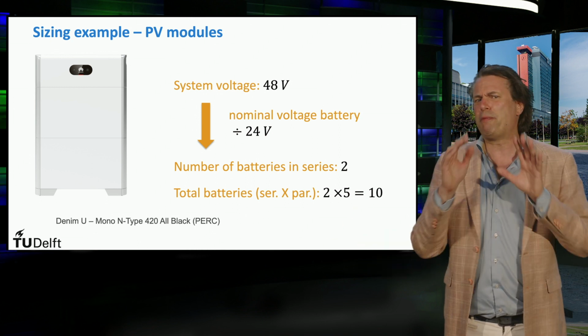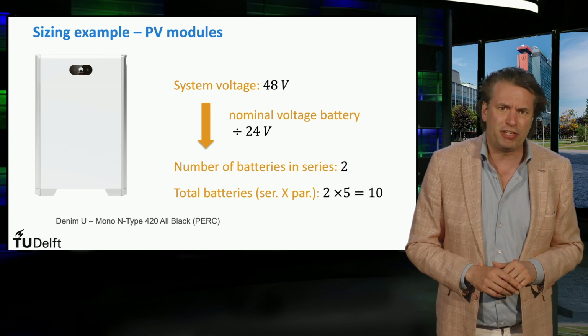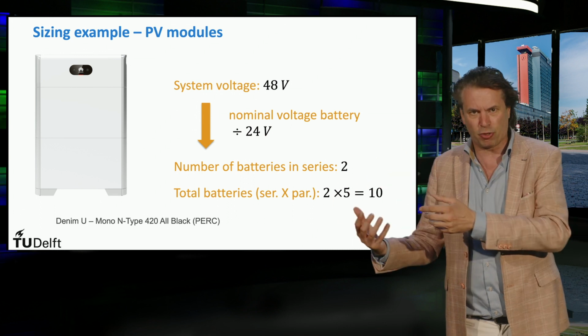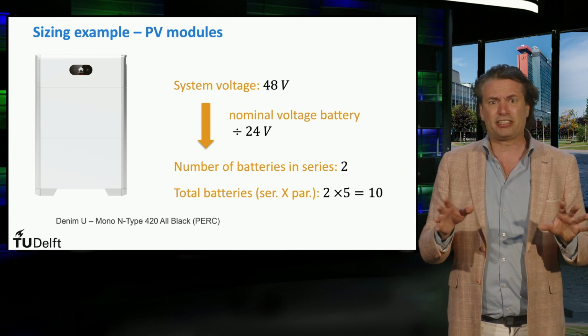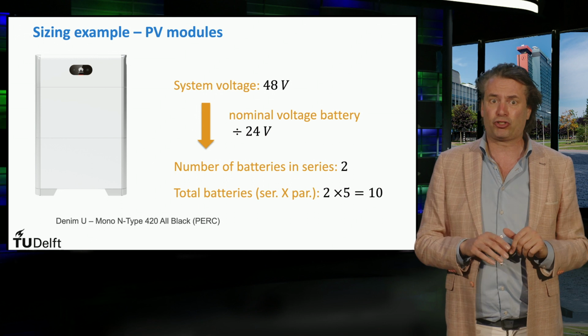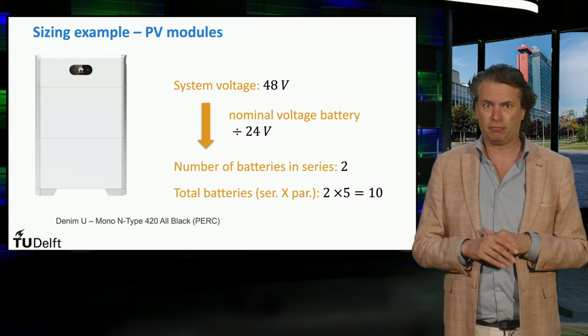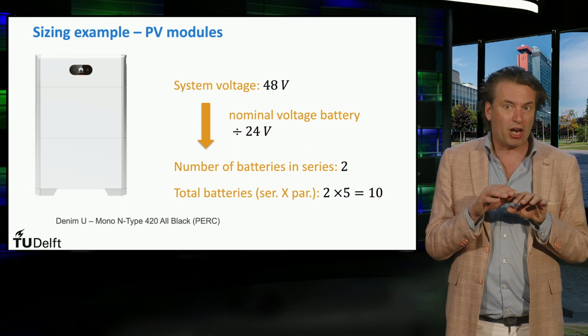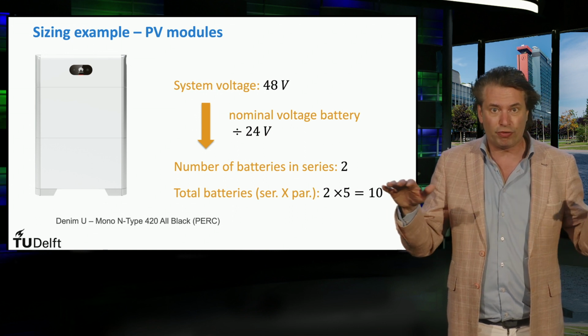So we have seen a simple method to design a standalone PV system based on the load requirements and available system components. Note that this is definitely not the most exhaustive way to design the PV system. This method works better for places with a more or less consistent irradiance level over the year.